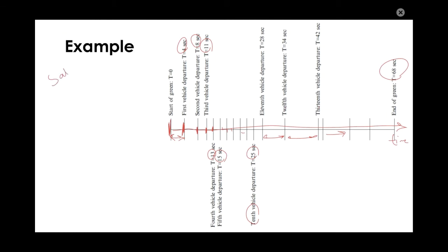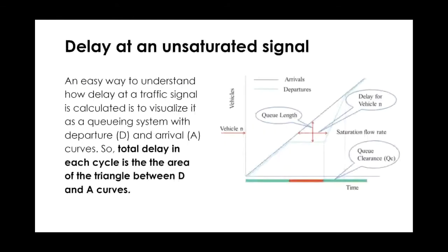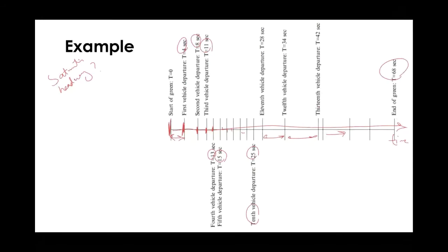I want to calculate the saturation headway here. Let's calculate the headways. From 4 seconds to 8 seconds, it's 4. From 8 seconds to 11, it's 3 seconds.